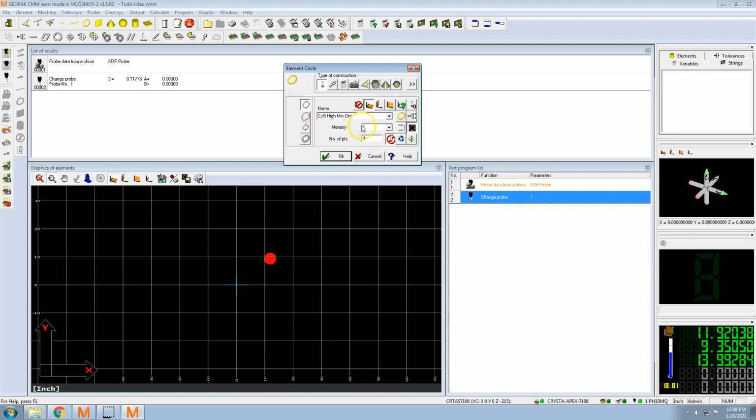4 is what I like. Now, this is so important to remember: name. When you're measuring 4 or 5 items, it's not going to make that big a difference. But if you're measuring 128 circles on this part, you're going to get real confused when you start looking through your readout on which circle is wrong. If you've got 1 out of 38 circles in the red, and you're trying to figure out which one it was, if you don't have a good name for them, it's going to be really confusing.